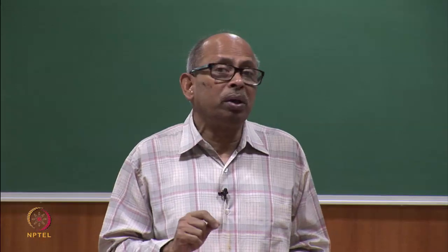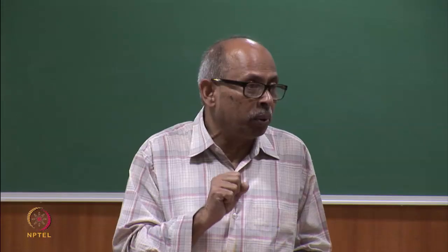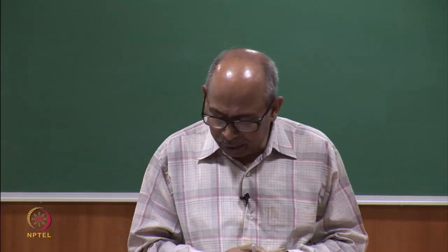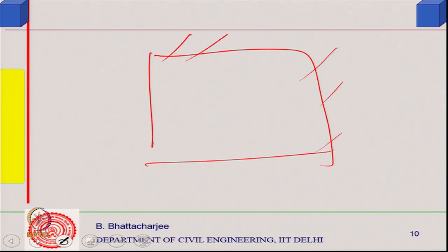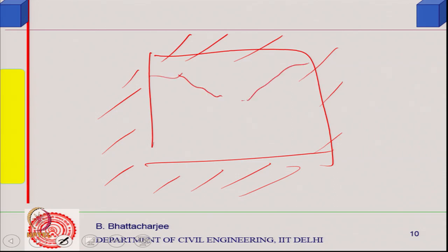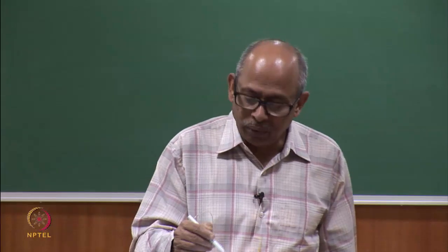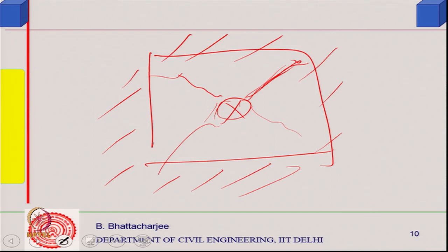The other aspect is, supposing you are taking a core, do not take the core from the most vulnerable portion. If you have a slab, say a two-way slab, and the failure plane, basically the crack, would be something of this kind. It would be better to avoid a core location like this, so that it does not lie on the expected yield lines, or crack lines or fracture lines or failure planes. So you would possibly take from somewhere else, but then you have to see also where the damage has occurred. So this is one aspect of it.